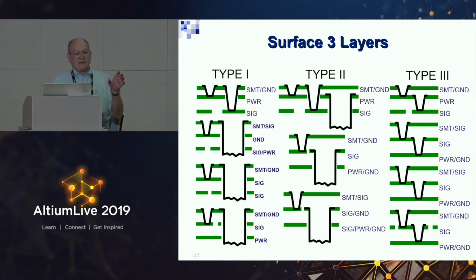I said, because fine pitch surface mount parts, even with a keep out, is smaller than a mechanically drilled anti-pad for layer 2. And so, especially electrical engineers don't have any concept of what a multilayer looks like on the inside. And they don't realize that by bringing that ground plane to the surface, they have a lower noise, better return path than when it's at layer 2. And believe me, I have endless fights about this for the last 40 years to convince electrical engineers that they're wrong, because they don't know what an anti-pad is.